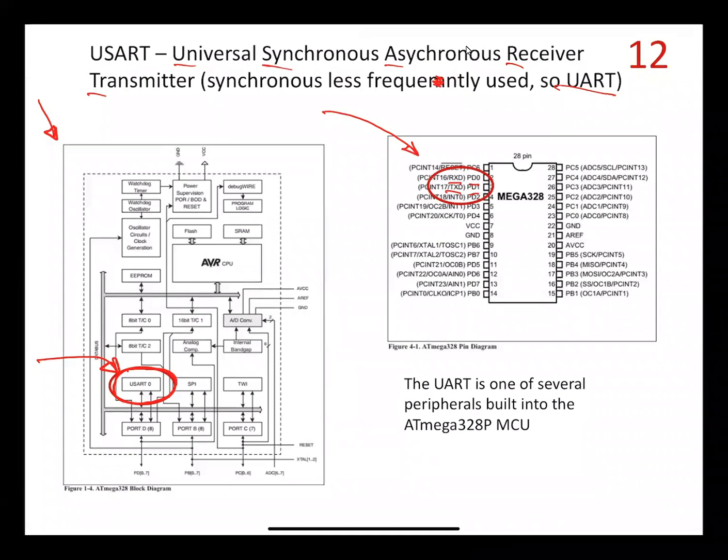And if it's enabled, then this part of the chip is actually up and running. And there is a potential issue for contention, or that is conflict between the port D functions for pins 0 and 1 and the serial communication functions if we're trying to do both at the same time. And we'll encounter that, and I'll walk you through that in a couple weeks.